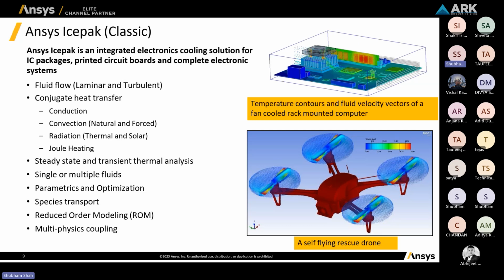Let's say you already have the data of solar radiation, at what particular time your solar rays are behaving, what heat flux is generated over a period of time, and how it varies with time. That also you can give as an input in terms of a UDF. You can enter it in a profile and go ahead with your own data as well.